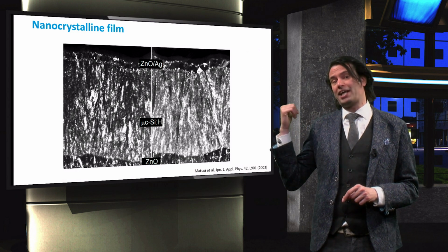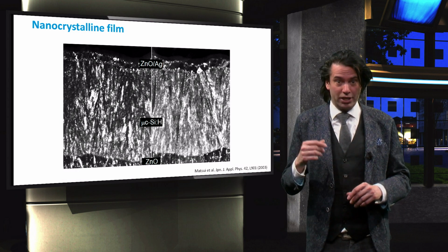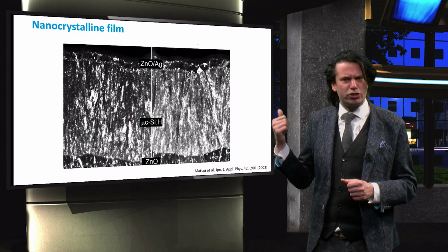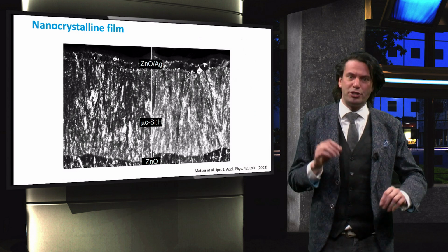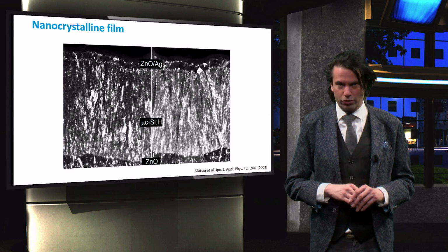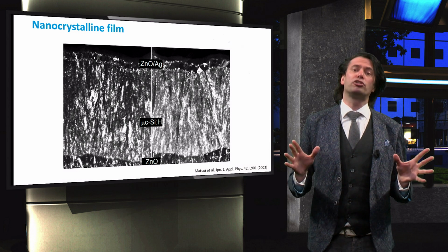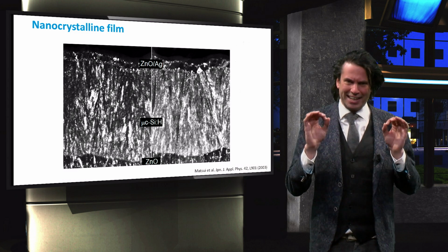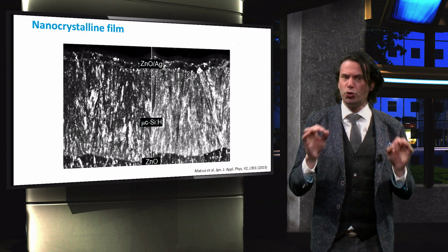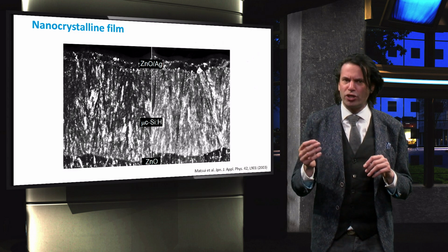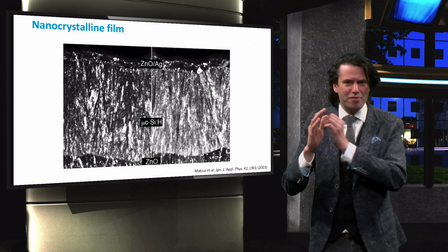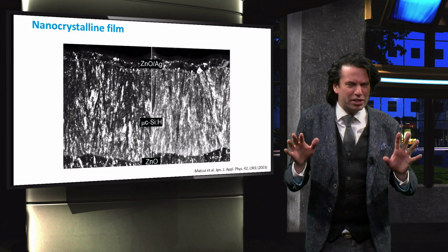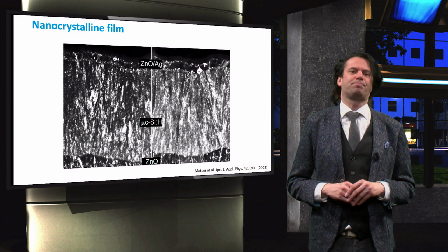An example of a nanocrystalline silicon layer with predominantly crystalline grains is shown in this image of a nanocrystalline silicon single junction cell, which is made using transmission electron microscopy. Research has shown that the best nanocrystalline building materials used in solar cells have a network close to the transition region between the nanocrystalline and amorphous silicon, with a crystallinity of about 60%.